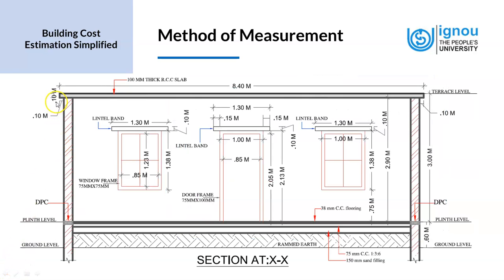When we look at it, we've got two dimensions, the length and the breadth of the roof slab. So in this we can see it's 8.4 meters, which is outer to outer edge of the roof slab. And the thickness of the roof slab is 0.1 meters. So we've got three dimensions in place. Let's look at the Excel sheet now.